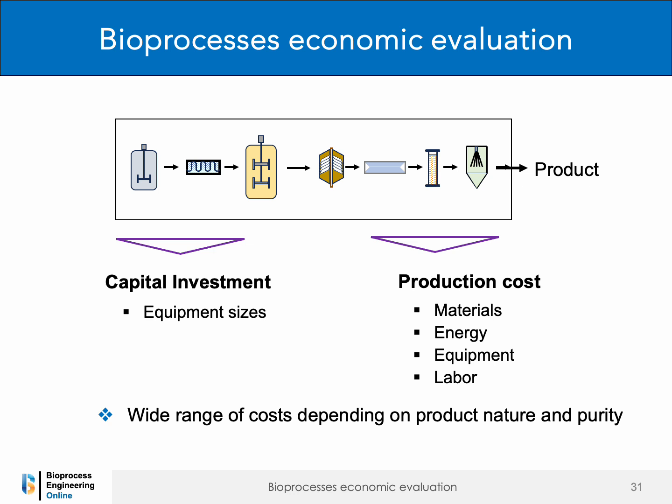In conclusion, in this introductory tutorial on bioprocess cost evaluation, you learned the methodology for assessing the capital investment required for bioprocess plants, based on equipment sizes. The methodology for evaluating bioprocess production costs, considering expenses related to materials, energy, equipment usage, and labor. As highlighted, production costs can vary significantly depending on the nature and purity of the product.